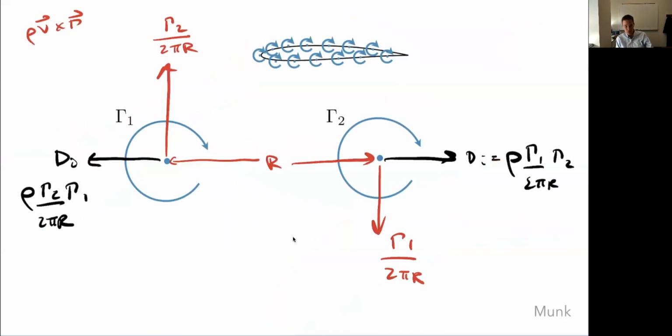And that's true of any pairs of bound vortices. So we could have any number of them, and if we consider the contribution from any, we could pair up every single one to sum them all up, and they will always cancel. So this one will cancel the effect of this on that and this on that. The effects on each other always cancel for drag. So in other words, for computing induced drag, what we've done is correct. It'll give us the right answer, even though the downwash is not actually right.